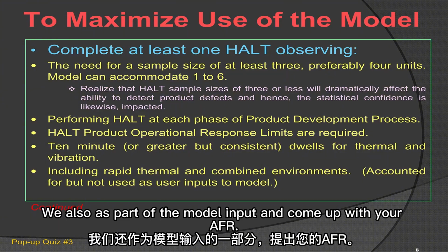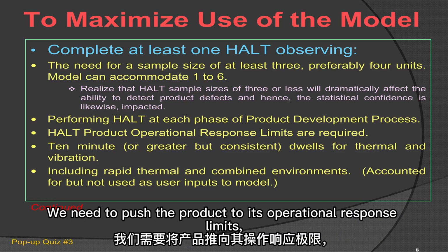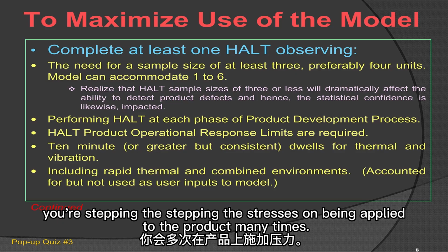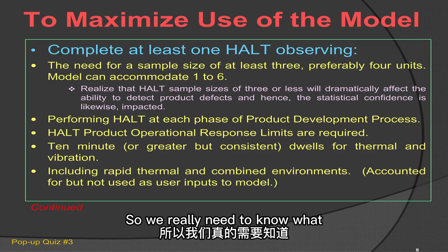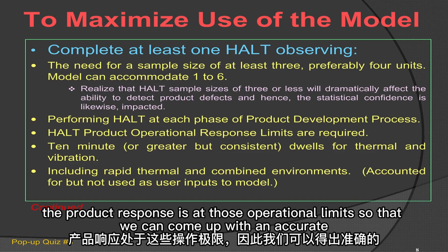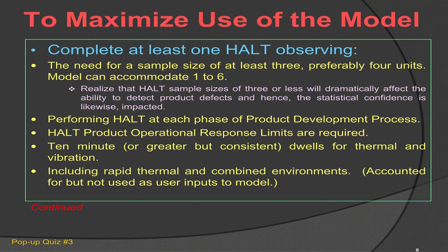We also, as part of the model to input and come up with your AFR, need to push the product to its operational response limits. In other words, you're stepping the stresses being applied to the product. Many times the chamber set point and the product's internal temperatures or stress are not the same. So we really need to know what the product response is at those operational limits so that we can come up with an accurate AFR for you.